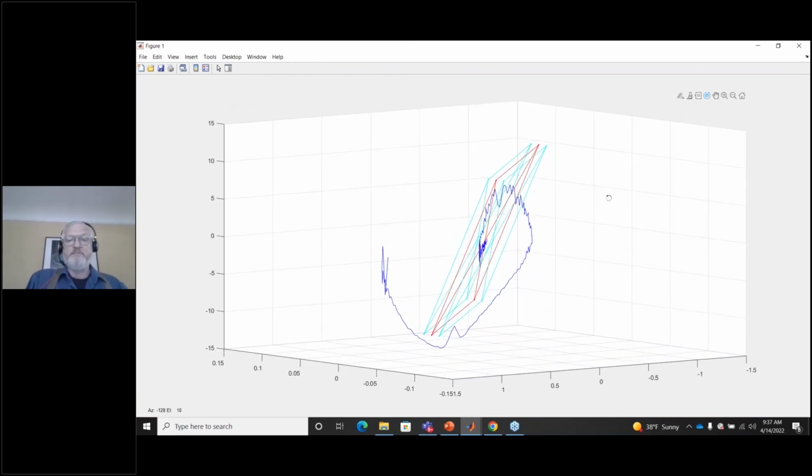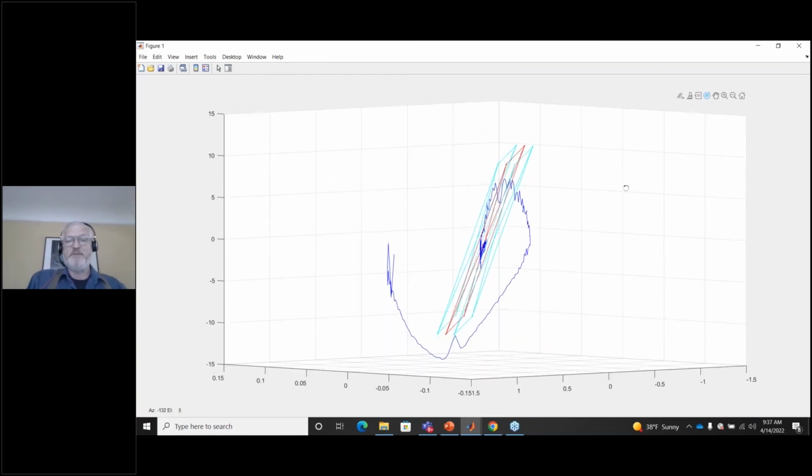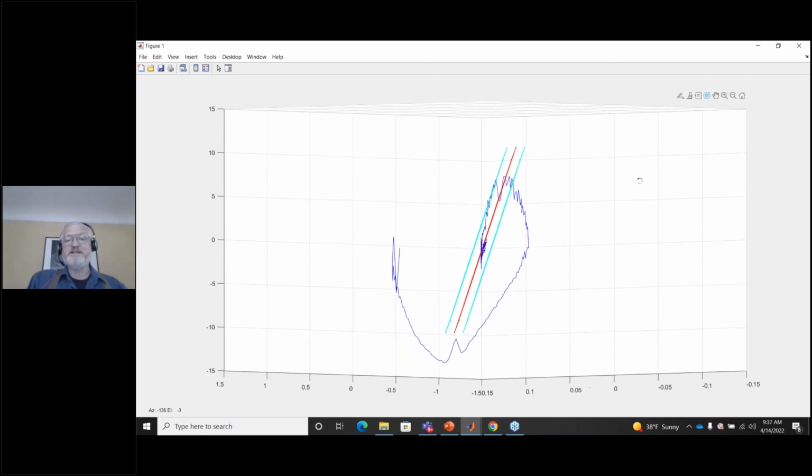And in MATLAB here, we can fly around the data set, but the compelling evidence that we're in sliding mode is the nonlinear behavior characteristic of the response. So we introduce a disturbance that takes the state far away from the origin. In error coordinates, of course, we should be steadily at the origin, and a majority of the points are in a small neighborhood of the origin here. But we disturb the system, and then the system responds. It's able to penetrate the sliding surface down here. It comes back around, and then it's captured by the sliding mode.